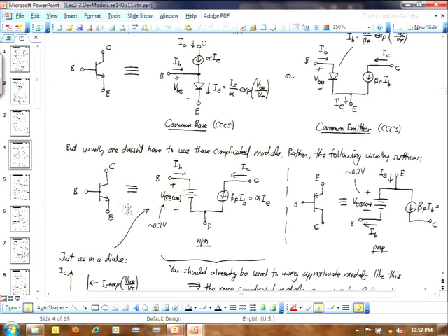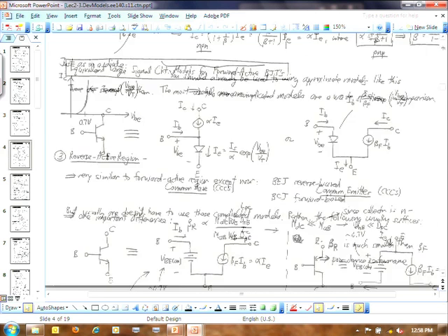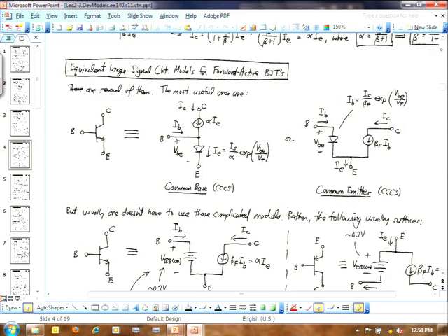If you have a bipolar transistor and it's forward active, then the equivalent DC model for it is a VBE on of about 0.7 volts. And then the VCE should be something larger than 0.2 volts. If it tries to drop below that, it's not going to get below, because the transistor will get out of forward active and suddenly become a saturated transistor. But those are special cases that you'll see very rarely. So that's forward active BJTs.